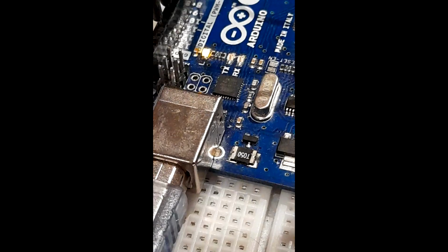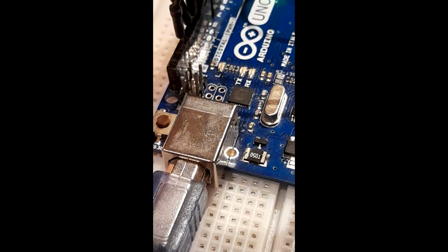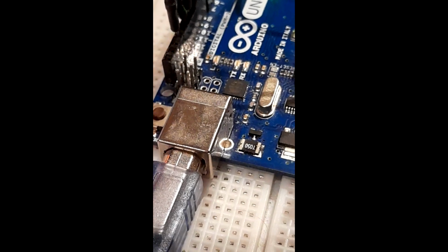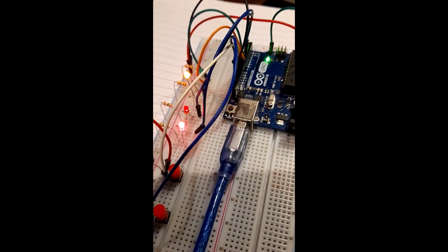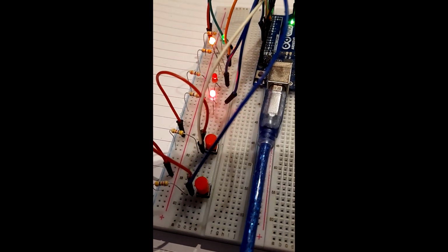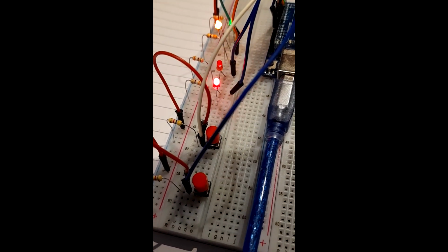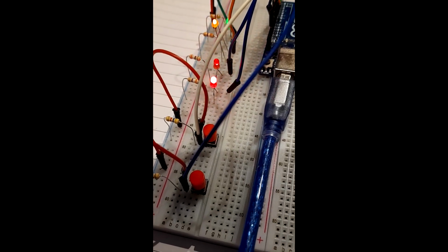And then on the board, I'm also flashing the board LED. I think it's once every half second, just to have something else running on. Obviously, there could be more effects running, but this is enough for now. Now, before, if you remember, when I pressed the button, because of the way the code was using endless delays, none of the button presses were recognized.